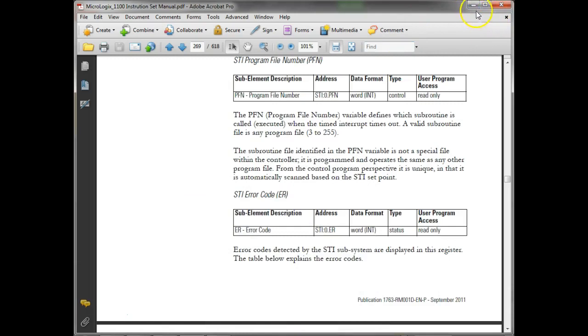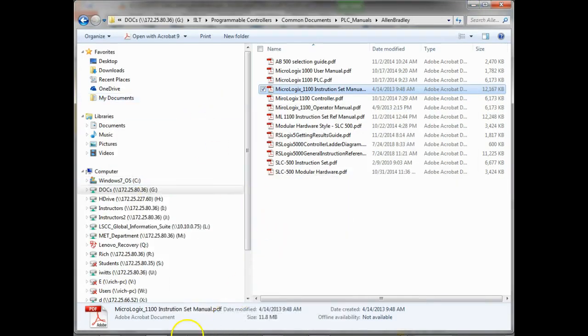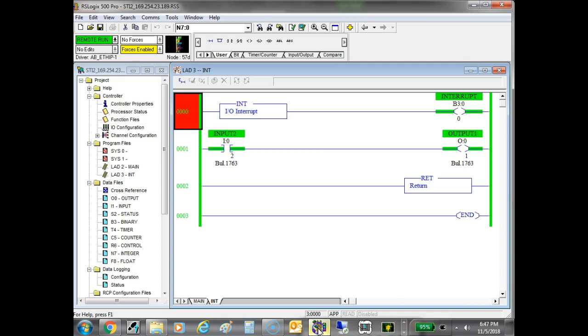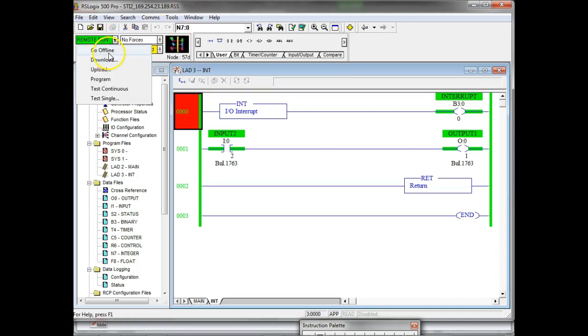is if it comes with a fixed number of inputs and outputs, right? You understand? But what they've taken away, guys, is this over here, because you're wasting memory. So I don't use R6. We will, but let's say I don't use R6. Well, we've already got memory dedicated to what? The R6, right? You understand? We don't use timers. Well, we've already got it dedicated to what? Timers.